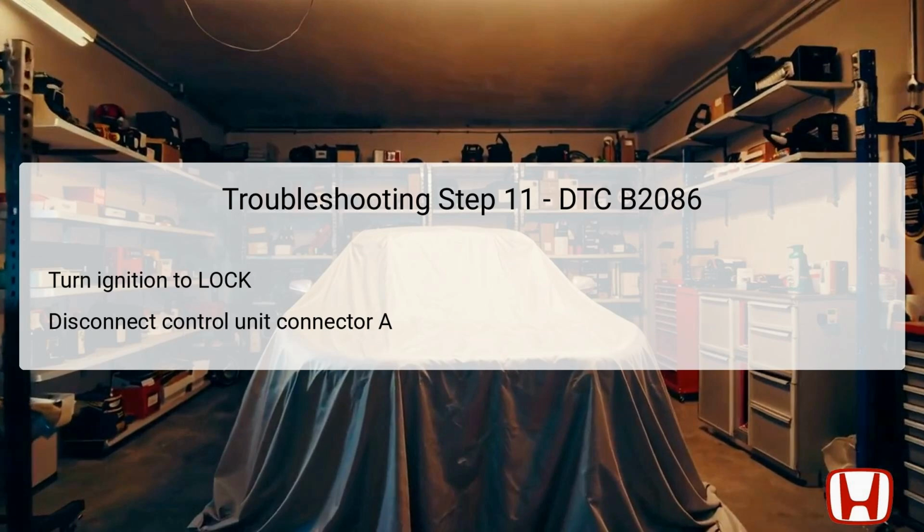By focusing specifically on the control unit, you can better isolate which component is responsible for the malfunction. Disconnecting this unit can also help identify if wiring between the control unit and other components is creating the fault. This step refines the diagnosis further by examining the control unit independently.